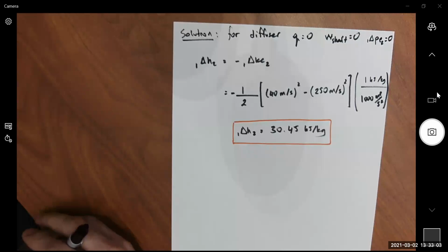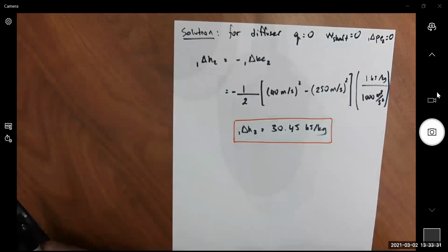Okay. So now I can find my enthalpy at the inlet, H1. It should be around 607, or I might be wrong. Knowing that my CP doesn't change too much as a function of temperature, in order for me to read CP from the table, I need my second temperature, which I don't know. So I will do reverse processing, trial and error, using CP being constant, almost. Clear?